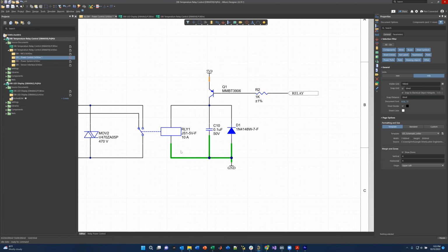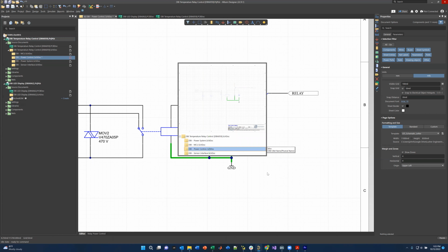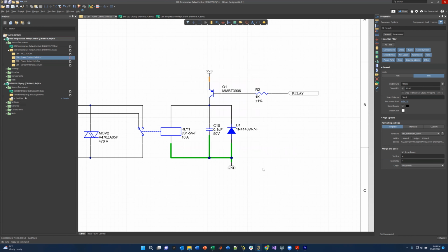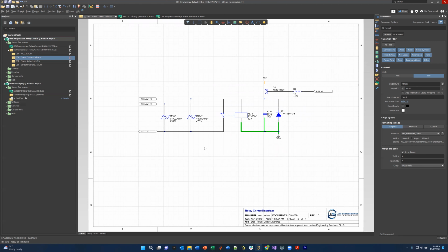And so being an inductor, it basically tries to keep the current flowing in the exact same direction, which means it builds back EMF or reverse voltage. So instead of 5 volts, positive, negative here, it'll be minus 5 volts immediately, in an instantaneous moment. That's not good for your power supplies to see. So just to prevent that, it's a good preventive measure: you put a capacitor and a diode in a reverse direction here, and that will suppress that spike immediately. So that is the relay control circuit.